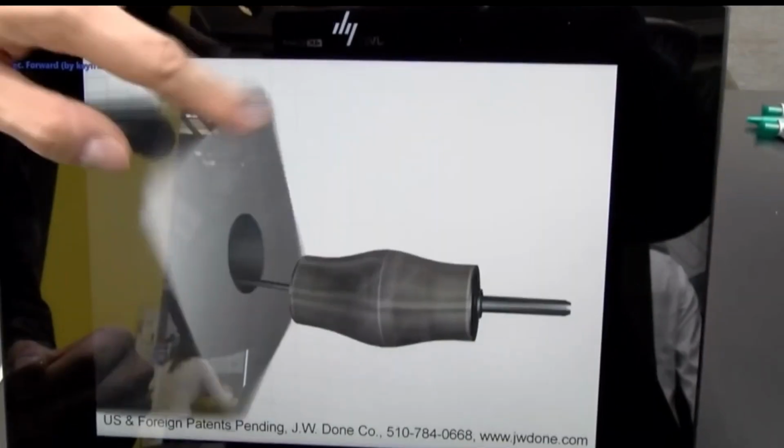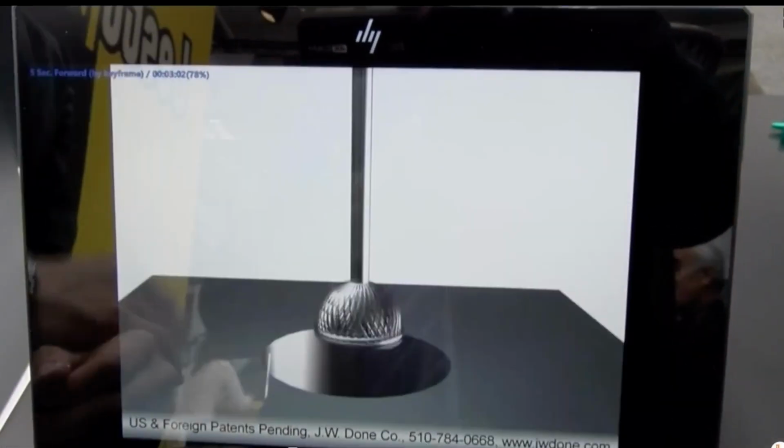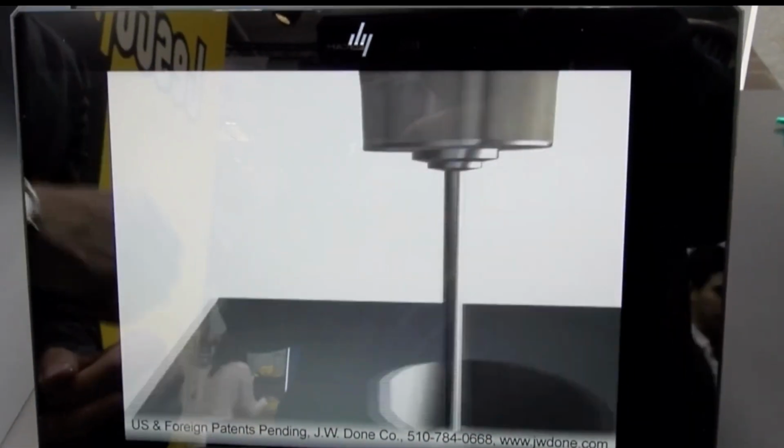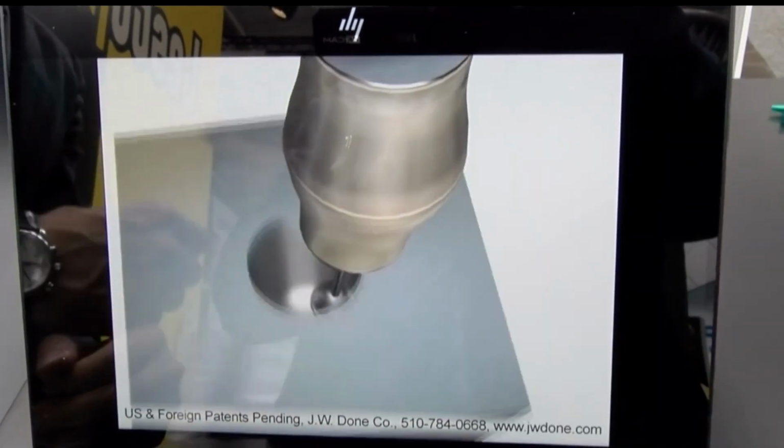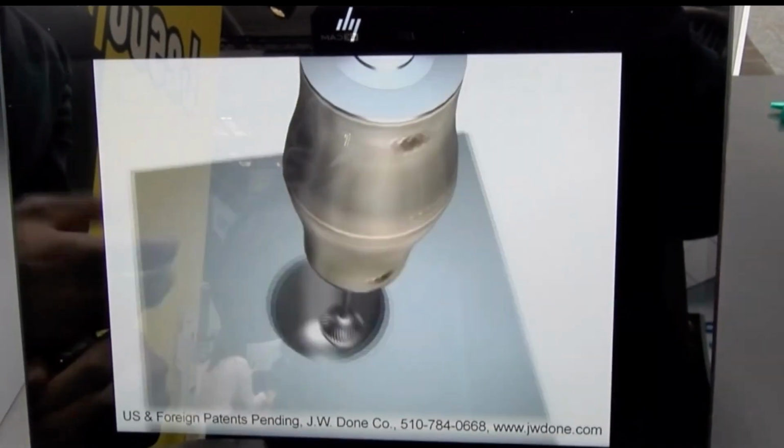We can fast forward a little bit to a mill setting. Same exact principle. We're making a threading motion on the inside of a hole. So either we interpolate the tool around that hole ID, or the tool is stationary and the part is rotating.